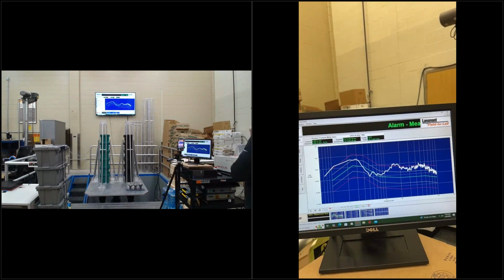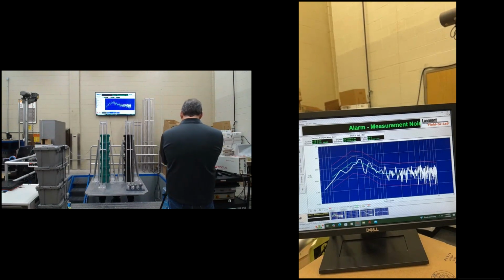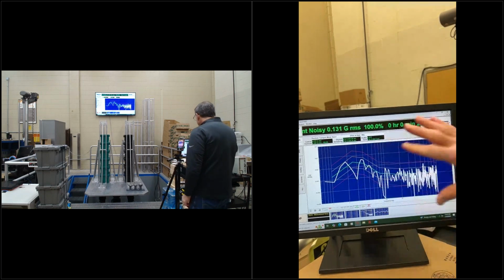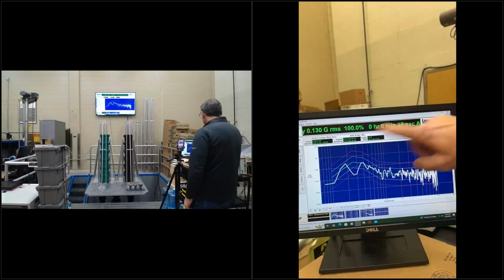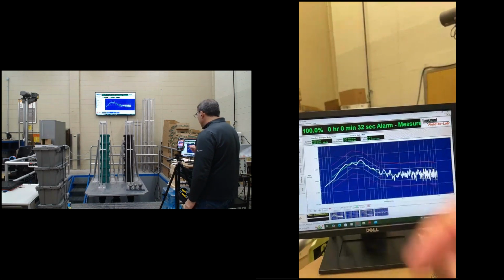This is the rail profile. This is the 3H rail profile, the most gentle of any of these profiles that are being run here. Low GRMS level, much less significant than anything that we've run here. And showing what that looks like on the screen. There's not a lot of any upper frequency characteristics associated with that, just this low frequency suspension input here.